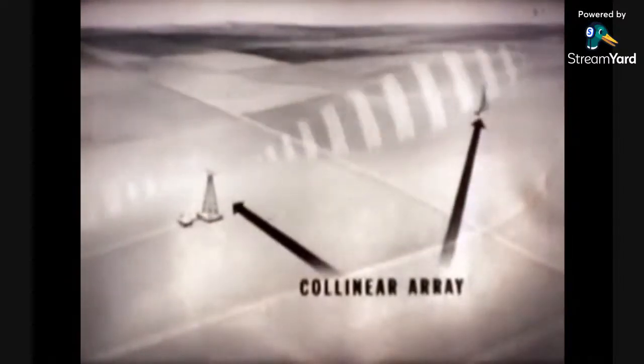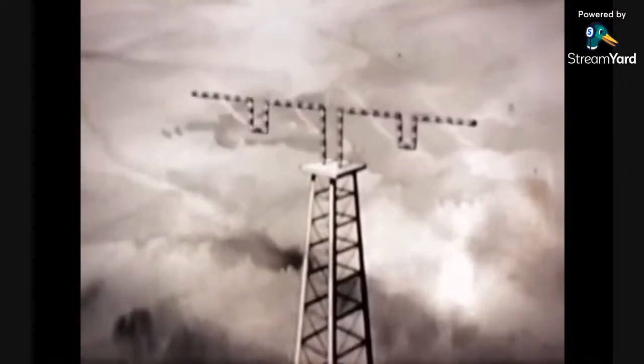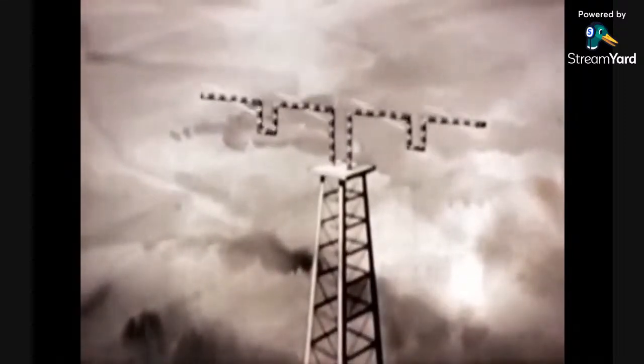The problem may be solved by using a collinear array antenna. Generally, this antenna is stationary. Physically, it can be quite small when very high-frequency channels are planned. The collinear array has two or more elements on a common axis. These elements are a half wave in length. They receive electrical signals of equal strength fed in phase.